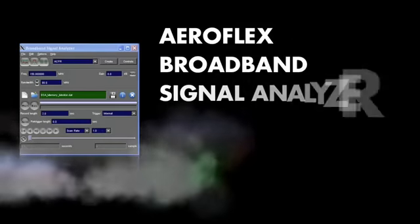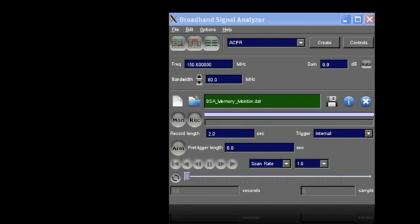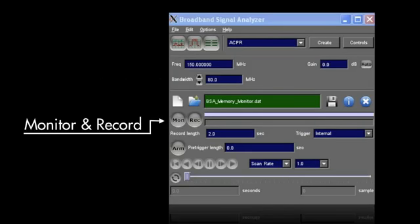The Aeroflex BSA broadband signal analyzer can monitor, analyze, and record RF signals. This first demonstration will show basic monitoring. Shown here is the BSA setup and control window. It has controls to toggle the display of the strip chart, spectrum, and numeric textual display windows. Also found in this window are the frequency control and bandwidth setting. Below this are the monitor and record controls.